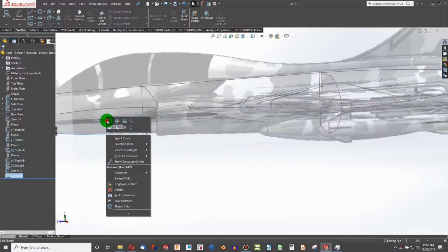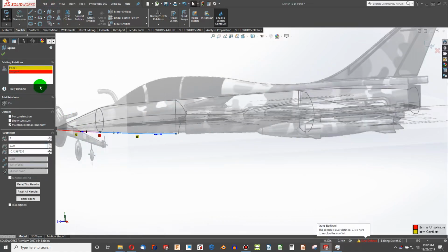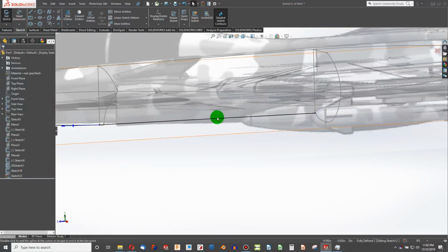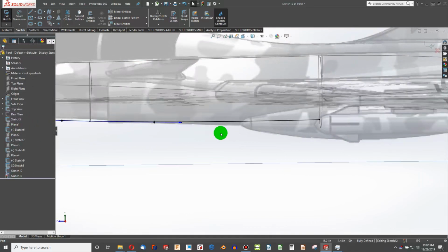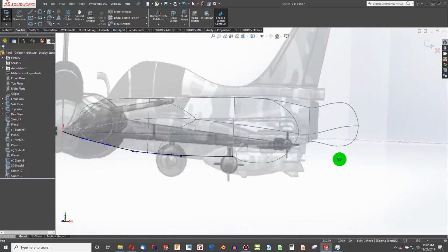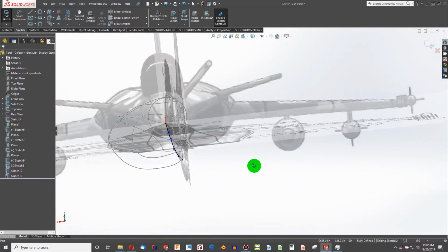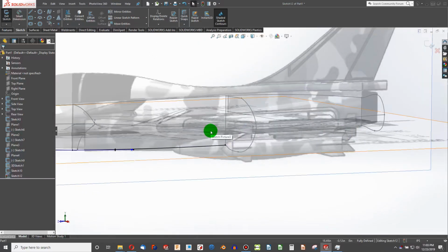Next, oh, and I got out of my sketch. I meant to just get a new spline, and also we're going to make this fixed and delete the tangent we don't need anymore. Tangent from here to the next profile. There. Of course, her body goes a little bit lower, which is to be expected.